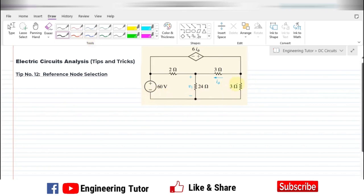So let us first draw the simplified version of this circuit. Now here we have 4 nodes, 1, 2, 3, and 4, and any of the nodes can be selected as a reference node. But which node to select? If we select this one, the voltage will be known here, but the other values we have to calculate. But if we select this one as our reference node, how would it simplify our problem?